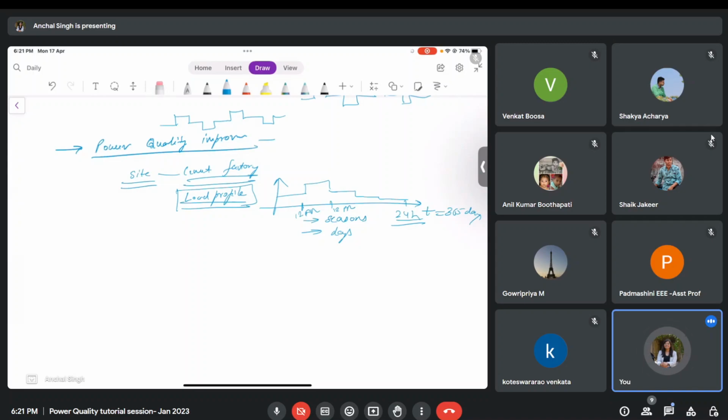You can also predict the load based on the past consumption. You can predict that this company will have this much amount of electricity bill next year. It is possible. So this load profiling, we go there and we do it. Then we do the PQ measurements, like the active power and reactive power. There are power quality analyzers. If you put one at the input of that factory, you can easily get these parameters: what is the reactive power that this factory is consuming, what is the power factor.